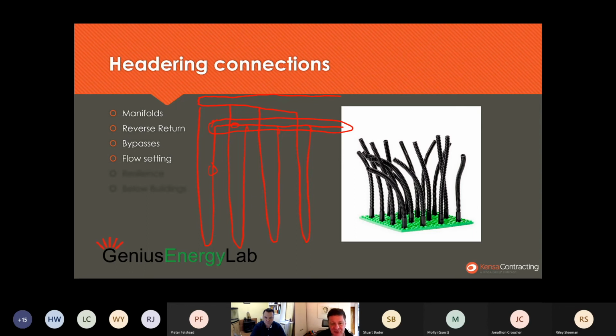So what you tend to do on these is, as you go past a borehole, you reduce in pipe size, so that on that last run there, you're at the same pipe size as in the borehole. So the pipe work on a reverse return manifold, a reverse return header, is a bit more complex than the pipe work in a manifolded system, but perfectly doable. I've designed hundreds of them over the years, and in larger commercial systems, it tends to be the most ubiquitous solution. Any other questions on that to that point?